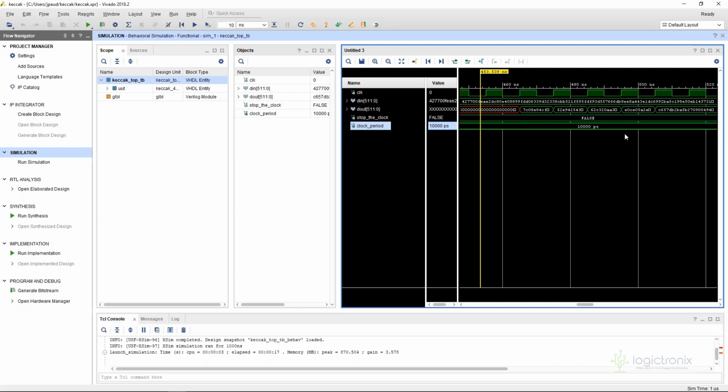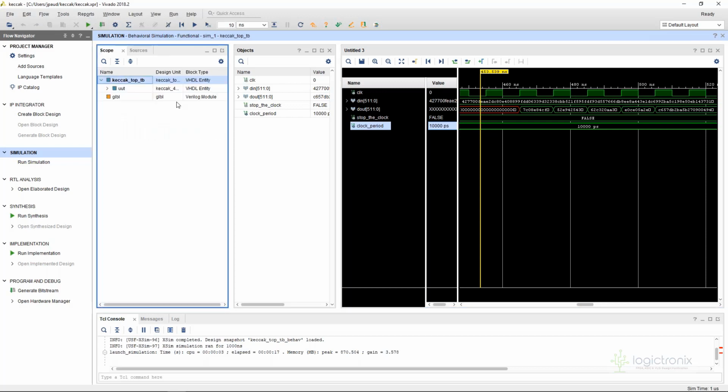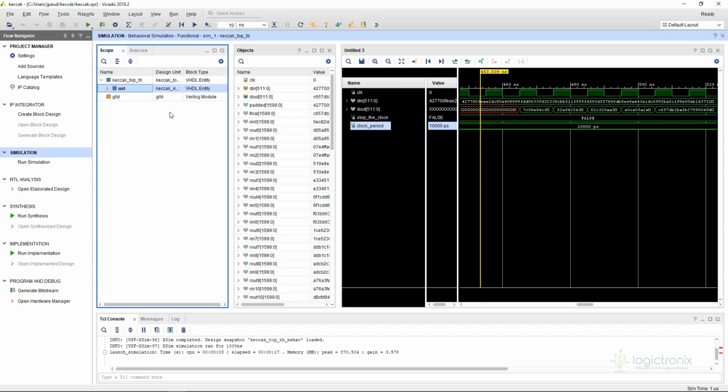And what is the hash rate currently we are achieving with Keccak, Jagannath? Okay, this single instance will result in 600 million hashes per second. But the plus point of it is this is utilizing around 4% of a high-end FPGA board like VCU 1525. Wow, that's really nice. Yeah, it's consuming too few resources, and we're getting 600 million hashes per second.